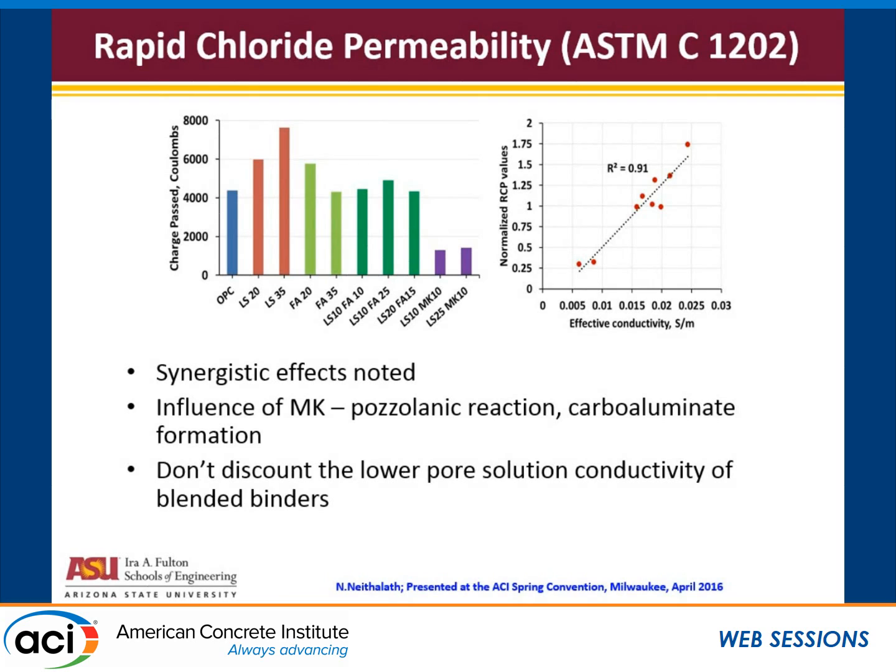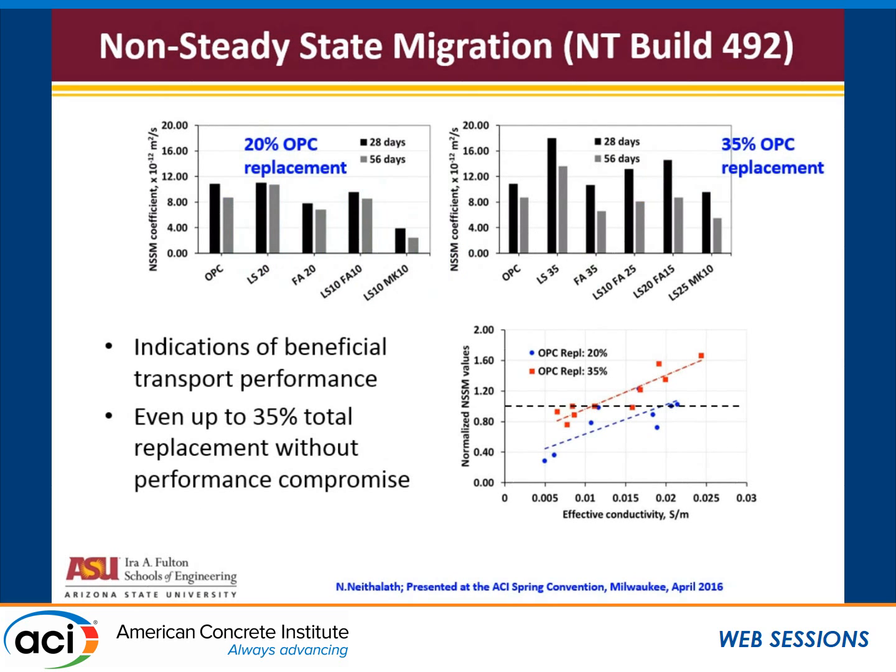If you look at non-steady state migration, which is actually a much better transport test than RCPT. RCPT takes 6 hours, this takes 24 hours typically. But it's a much better transport test because you're not pushing in the ions at a 60 volt voltage.